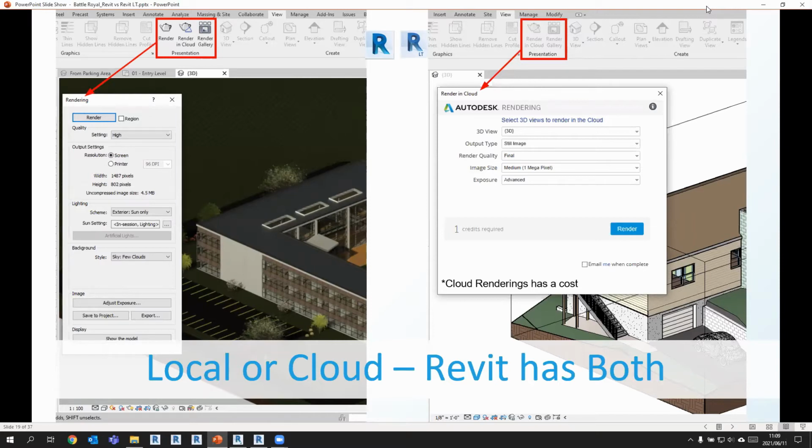But this is an important thing to understand. On top of this rendering plan, because Enscape and Twinmotion, as being one of our questions, are very reliant on plugins, it does become quite difficult to use Enscape with Revit LT, or actually impossible. And with Twinmotion, you do have to navigate a different export out of Revit LT.